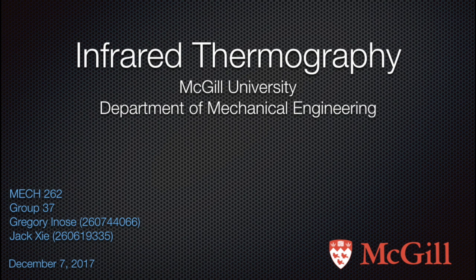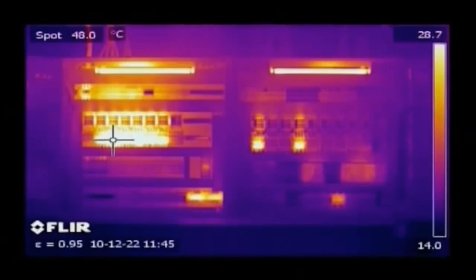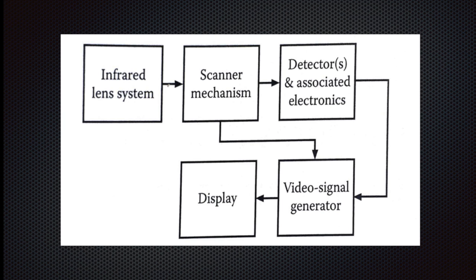Infrared thermography, also sometimes known generally as radiation thermometry, is a non-contact temperature measurement technique that makes use of the correlating relationship between the amount of infrared radiation that is emitted by objects and that object's temperature. The general physical operating principle of these devices is to convert radiated energy into heat and then into an electrical signal proportional to the amount of infrared radiation.